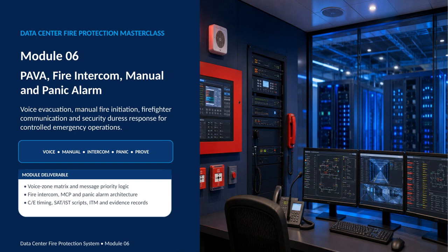We'll develop a voice zone matrix and define message priority logic, so the right information reaches the right areas at the right time. We'll also examine the architecture linking fire intercoms, manual call points, and panic alarm devices. The module deliverables extend beyond design. They include commissioning and evidence activities, such as C&E timing, SAT and IST scripts, inspection, testing, and maintenance records. By the end, the focus is on a system that can be operated, tested, documented, and relied on during an